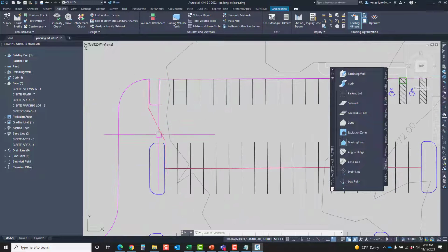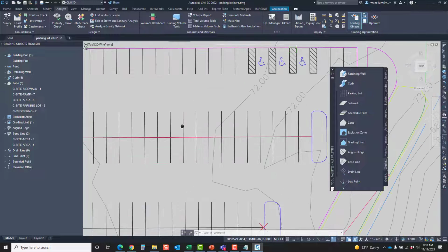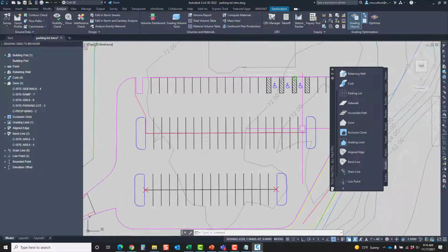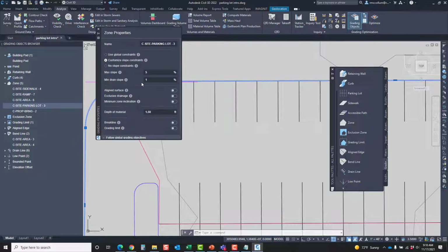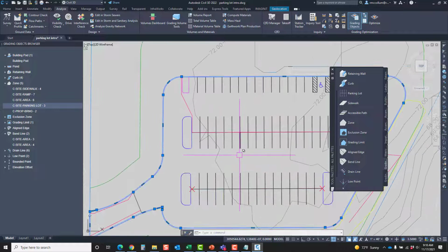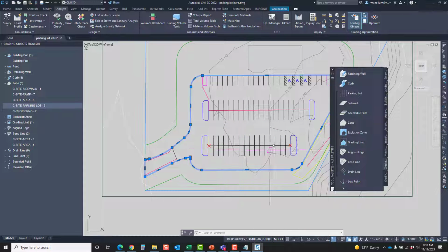So I've set up some of those. You can see right here. I have lines that come down here, so there'll be a catch basin right here to pick up flow, and anything this can't pick up, I've then drawn a line from here to here to flow to this point, and then based on the cross slope, the slope settings of the zone itself in which it's in, it'll pitch the entire surface toward it between 1 and 5%. Same with low points that I could place in that are just going to basically be cones of depression around the local area, that will do the same thing.